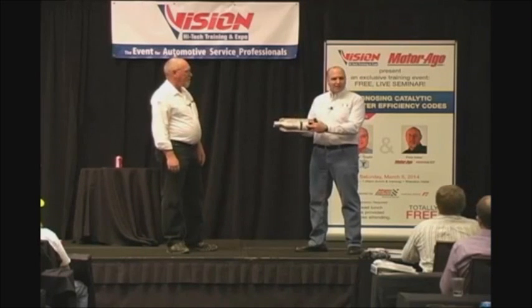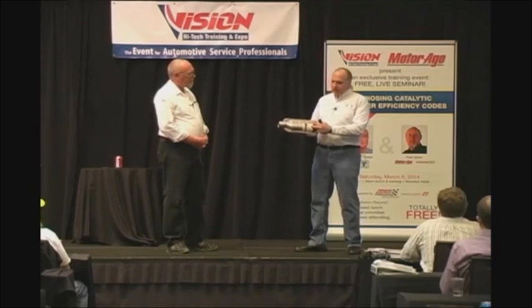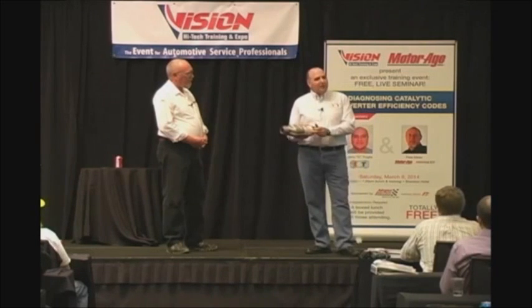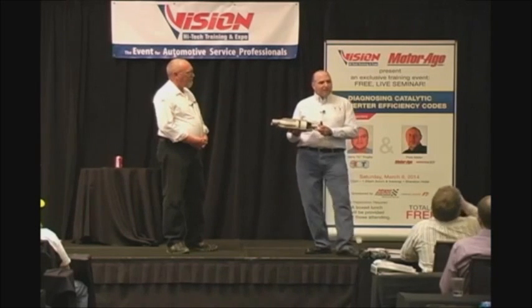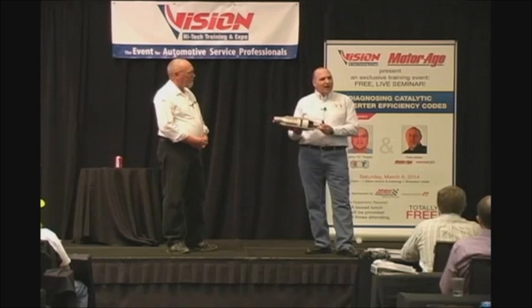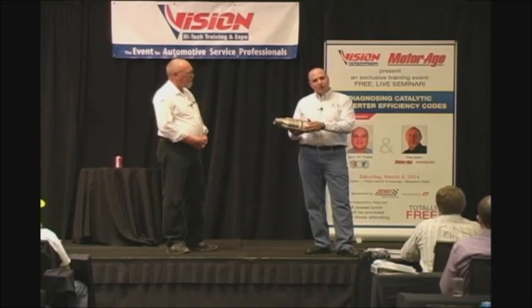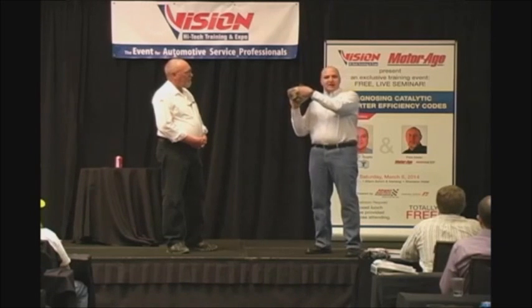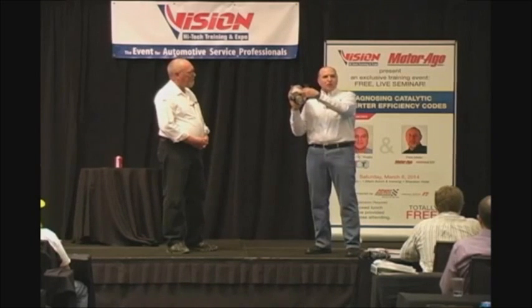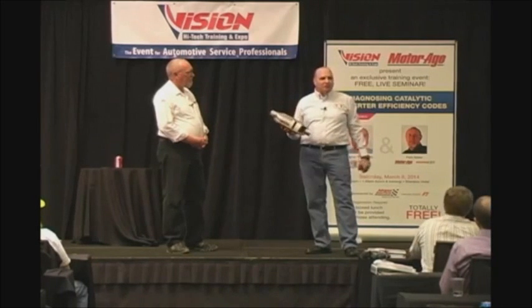Now, I'll give you another one. The matting of a converter is very important, okay? I'll give you an example on a BMW on their 8-cylinder cars. You go down the road, and if you don't give it a pedal to the metal, it'll be okay. You hit it hard, and what happens? These were OE cats, and the matting from the manufacturer wasn't really good. It started breaking apart. The cat twisted sideways, can't get through the substrate, and now this car's dying down.